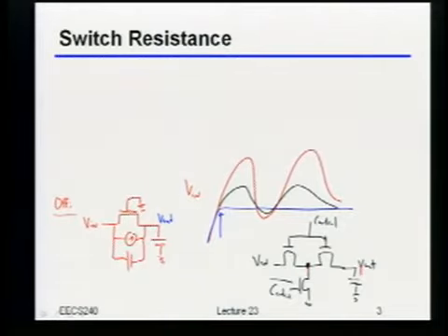Okay? So by the way, this is known as a T switch. And in applications where, again, you really need very high isolation on the sampling, you may indeed actually have to implement things using this T type of structure. And you should keep in mind, I drew this as ground here. It doesn't actually have to be ground. It's really just whatever your output is sort of quote-unquote referenced to.